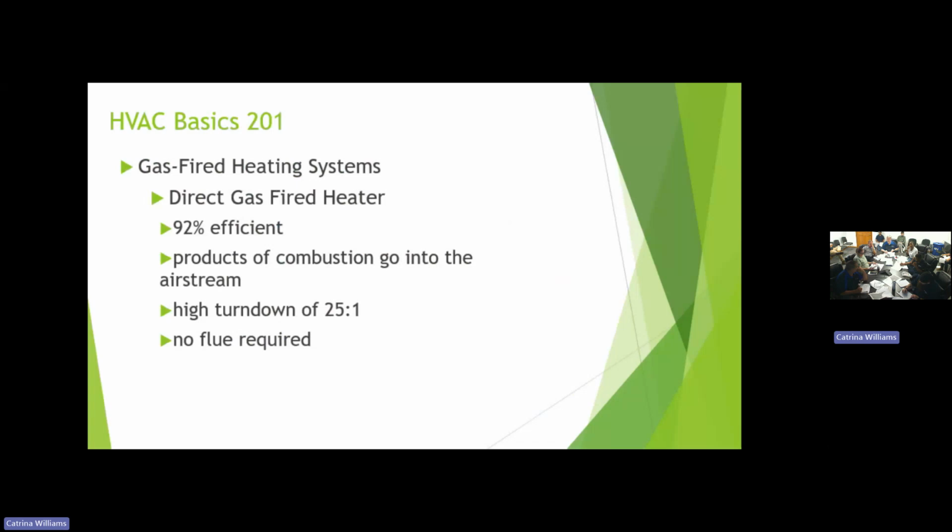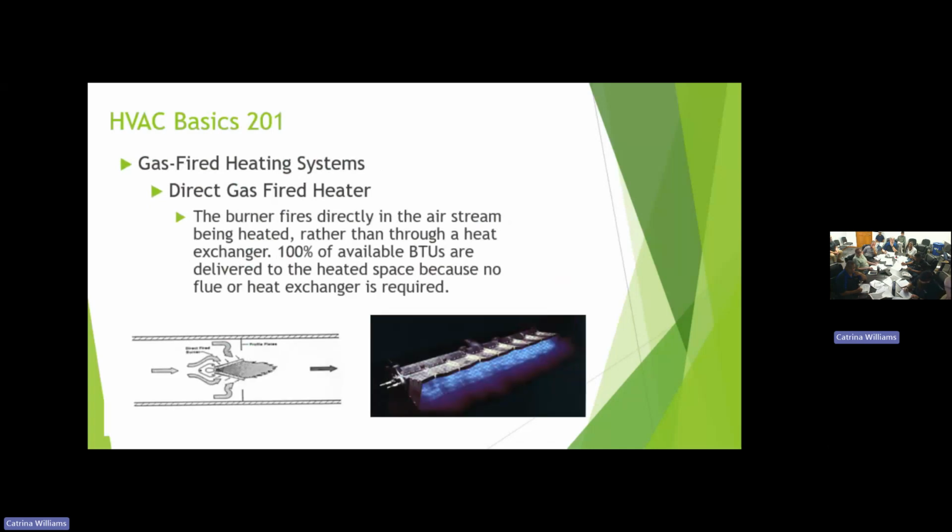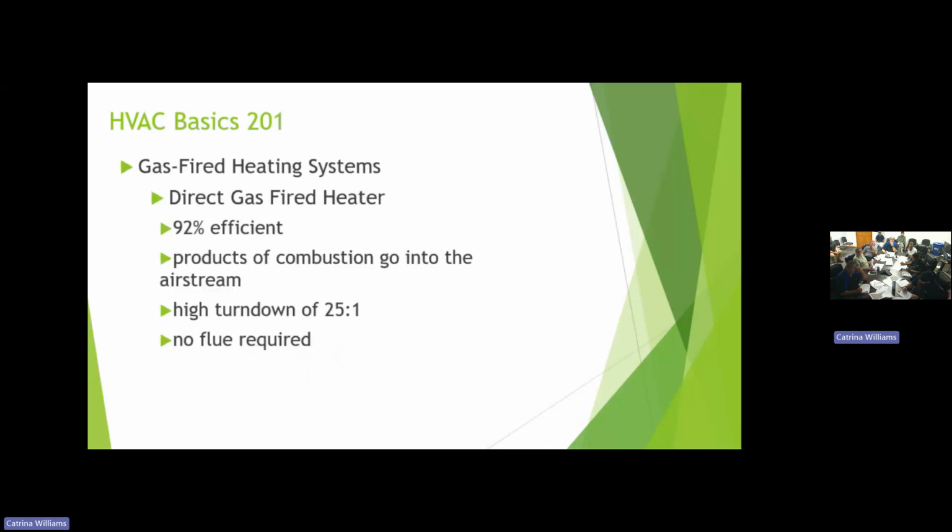So if they're trying to ask on a gas-fired, what's the lowest the turn down can do so that they know how far the flame's going out, you would take the 25% of whatever the highest turn down is. And that's the lowest it can be to be safe. If you try to go lower than that, you'll have what we call blowout after a certain point in that cast iron burner that I'm pointing at. It won't be a continuous flame across there because it's too low to have that one ribbon. And it becomes dangerous. You'll have gas coming out, but it's not being burnt. So 25 to 1 is the number that we stick with.